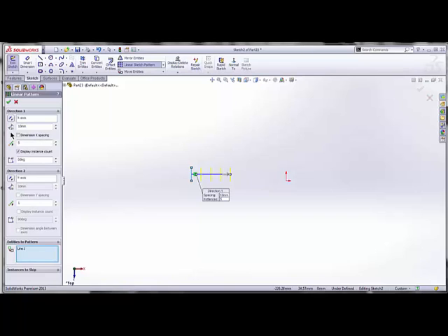And you can increase or decrease the spacing between these instances. The spacing here you can see is 10 millimeters. If you increase it to 20, as you can see the gaps between these lines are increasing. If you decrease it, the gaps will decrease. So this is in x direction.